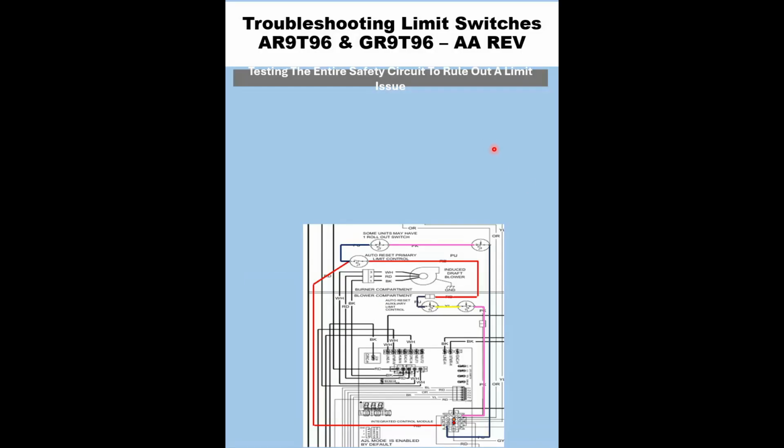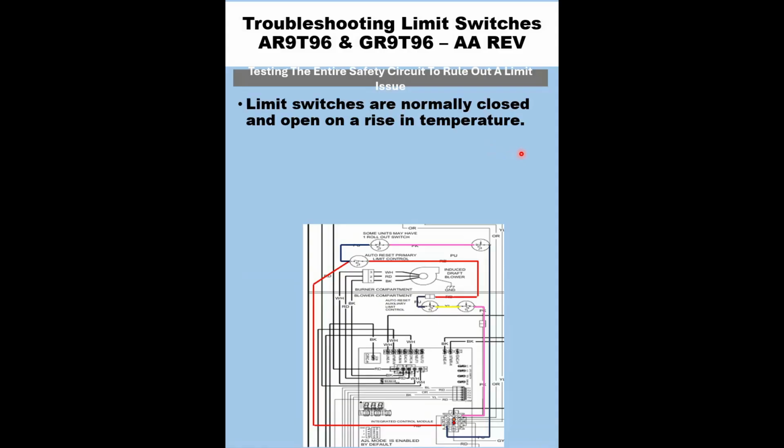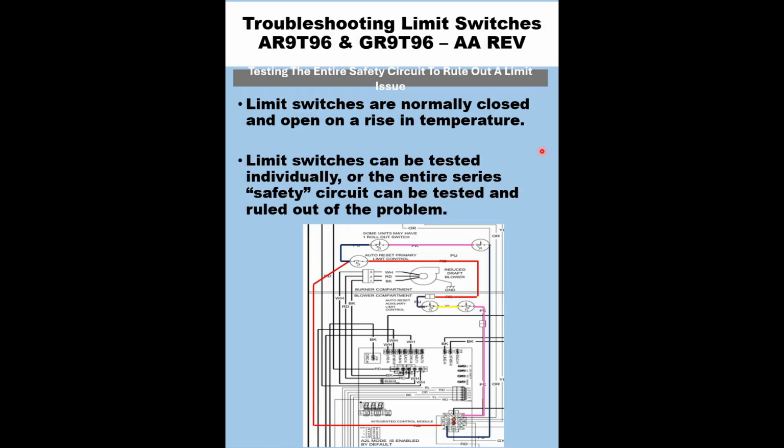Testing the entire safety circuit to rule out a limit issue. Limit switches are normally closed and open on a rise in temperature. Limit switches can be tested individually, or the entire series safety circuit can be tested and ruled out of the problem.